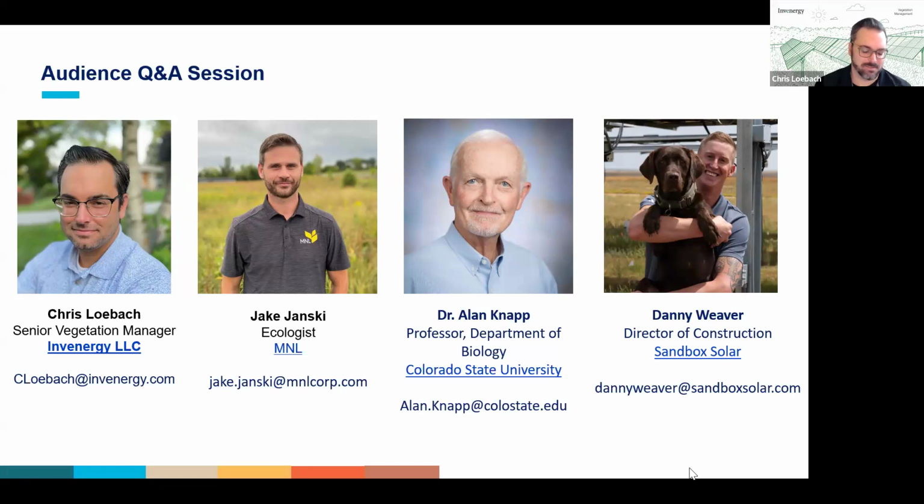So that's why in my talk I said this is really focused on my experience in the upper Midwest. I don't really work out in the arid West. I don't really know it as well, but I do know the top priority is to preserve the vegetation that's already there. We'll still do some seeding if that's needed, but there's way more of an emphasis on preserving existing vegetation versus the upper Midwest.